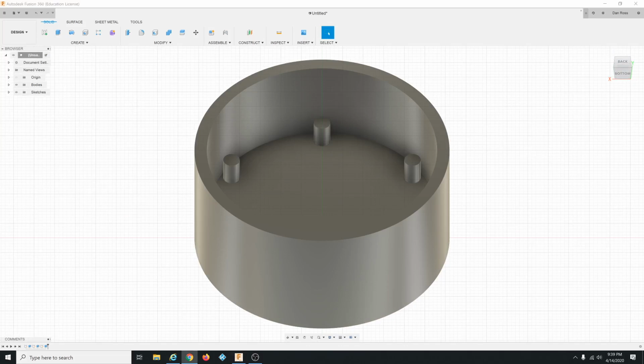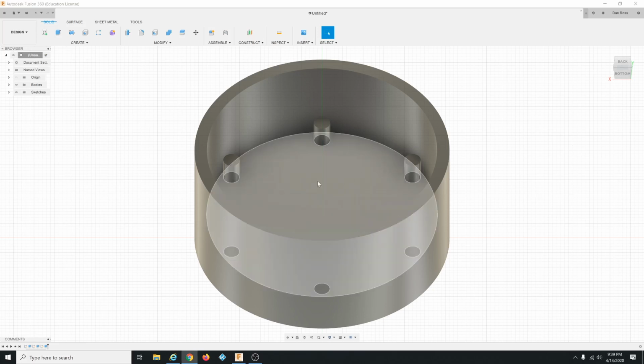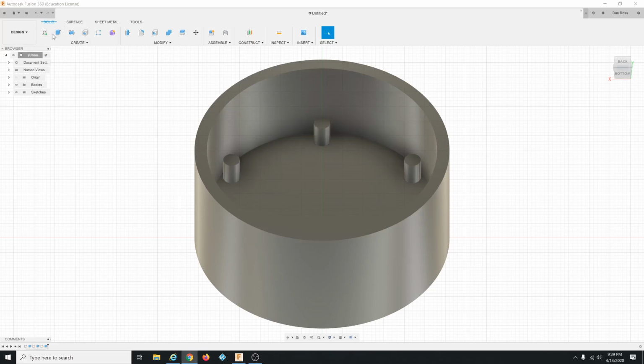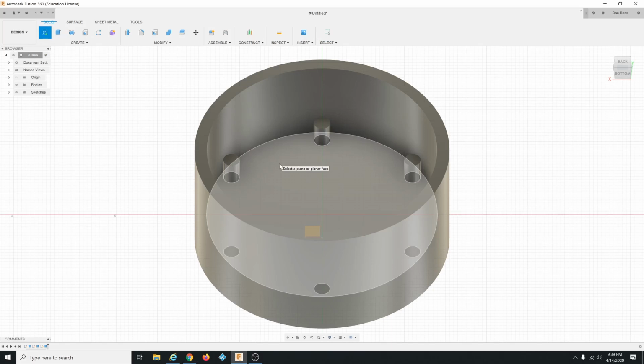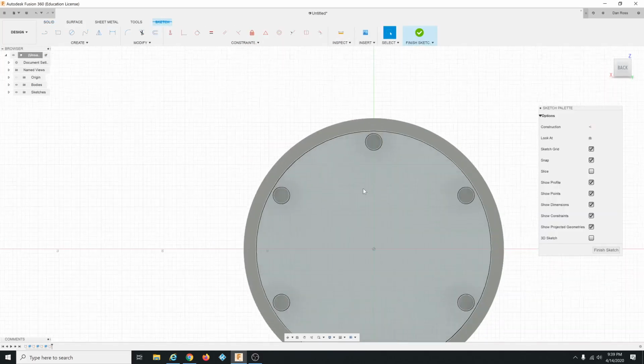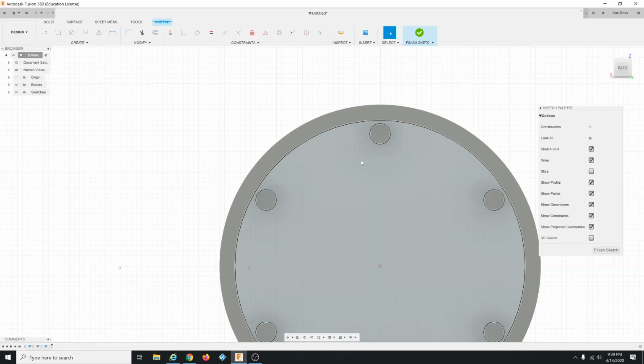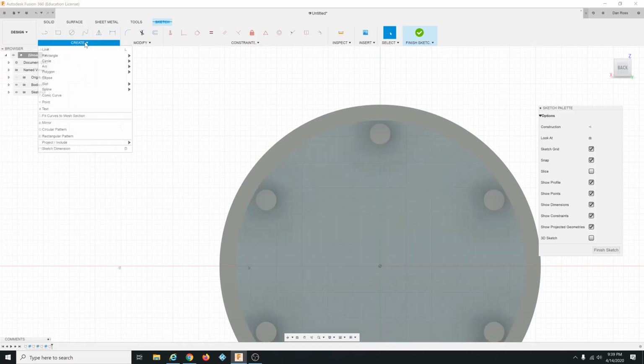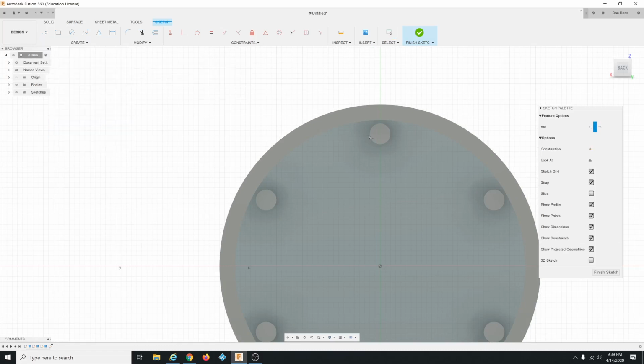Time for another sketch to do. Well, that was activity 2. So activity 3, we're going to do these arcs. Okay, so new sketch. Click create sketch. Click this plane. It does this orientation thing for you. Then go up here to create arc, 3-point arc. Click center of the circle.